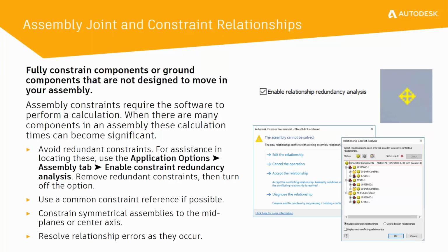So don't get in the habit of just ignoring relationship errors. If it's an error, try and fix it, because potentially that's adding additional system resources to try and look at that error and try and resolve it.